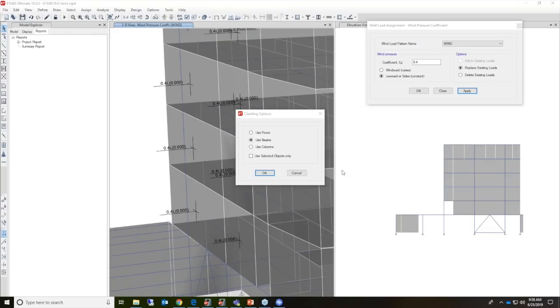Shall we define different load combinations when using a code other than ASCE 7-10, positive and negative values for wind load? When the program automatically calculates the design load combinations, we do have positive and negative values used in separate load combinations. If the user is defining them themselves, they should have load combinations, one for the positive direction and one for the negative direction.